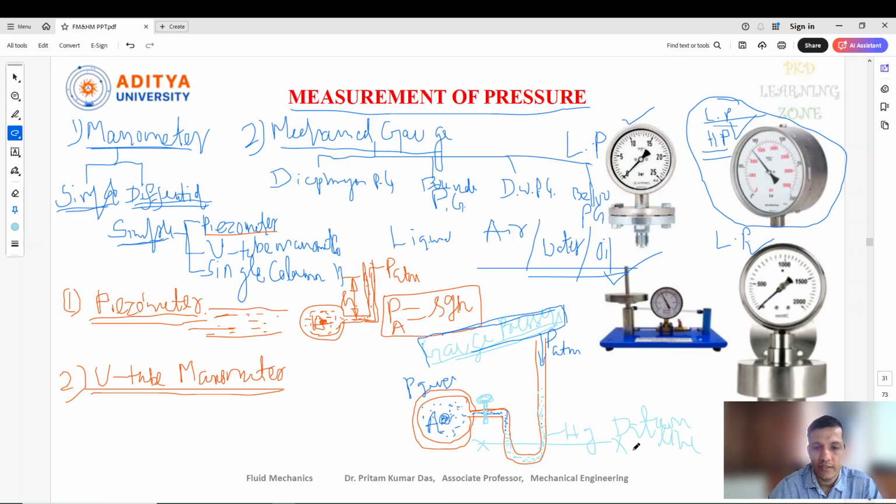After the liquid flows inside the pipe, the height of the liquid giving an impact on the mercury, from the center point to the datum line, we call H1. Due to this impact, the rise in the mercury up to this level we call H2.